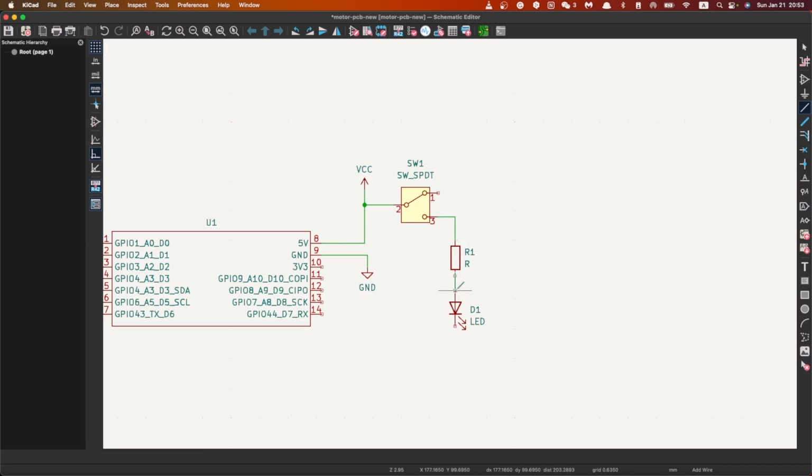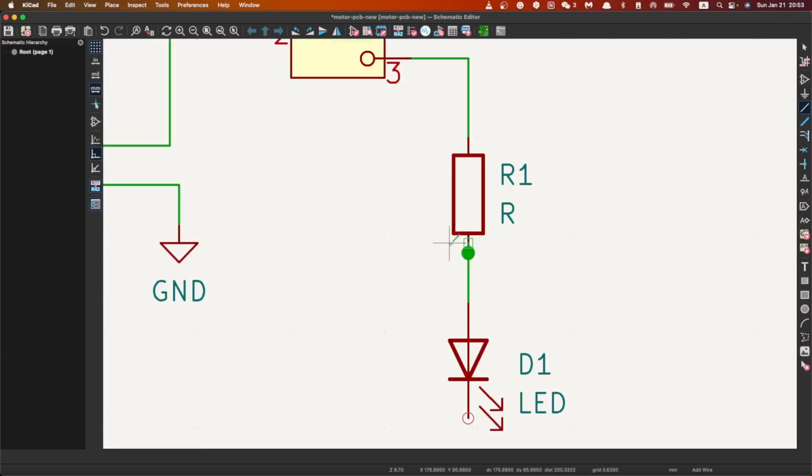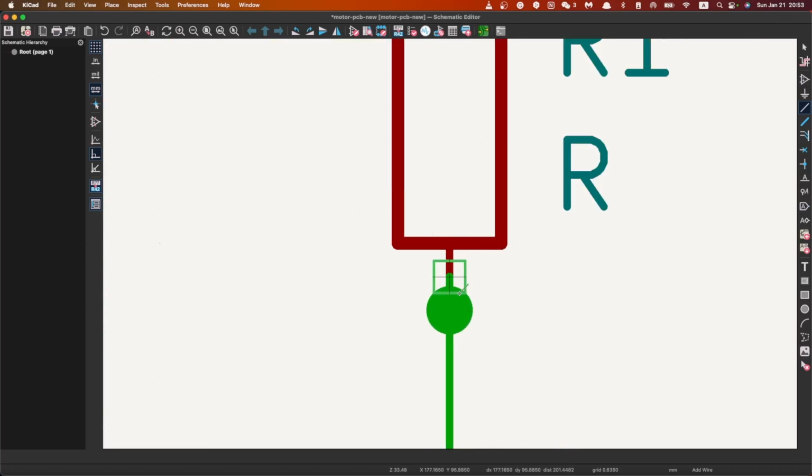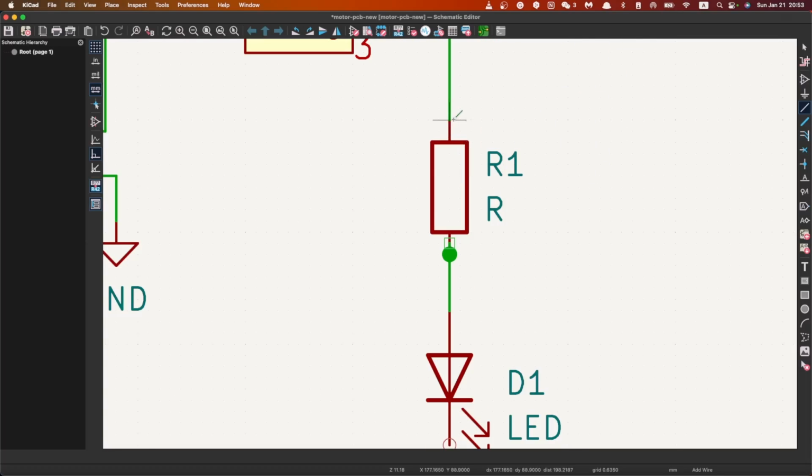Then connecting them all together, and see, I've misclicked it, and there's a square here, which means it is not perfectly connected to the circle pin there. Because if they are correct, the circle pin there should disappear. So Control Z, I'm gonna revert and then fix it.